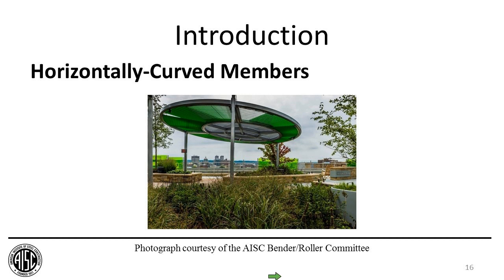Now this is my favorite one, and the reason is partially because it looks like a UFO, and partially because it shows a lot of things that we're going to be talking about. For example, this goes the whole 360 degrees with only 3 supports here. And so you have a really wide span angle on this horizontally curved member. And you'll notice that if you look closely, and I'm not sure if they did this for the aesthetic effect or for the torsional stiffness, but that's an HSS member.